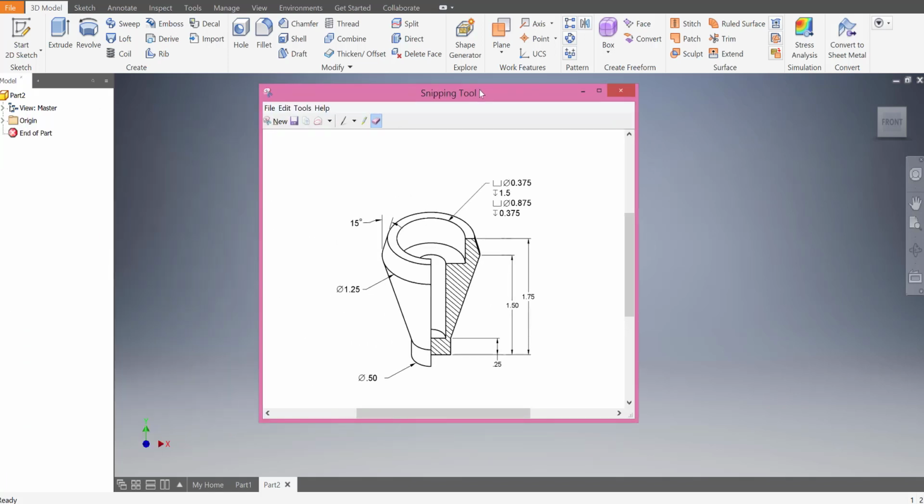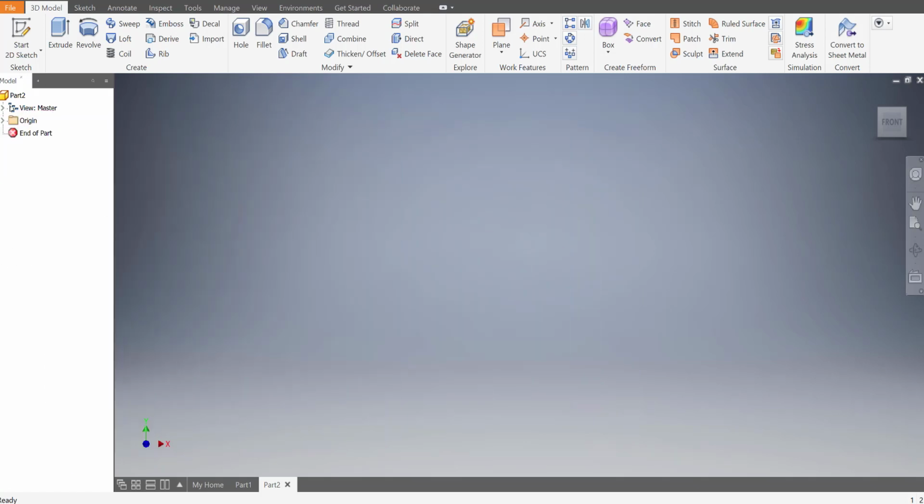In this tutorial we are going to make this smokestack. To begin, they give us the section view of it. Whenever they give you the section view, it's oftentimes a good idea to draw that out, because if you draw it out, you can usually revolve it around the center, and if you revolve it around the center, you essentially create the entire thing. So we can make this maybe in one step. So let's go ahead and give that a try.